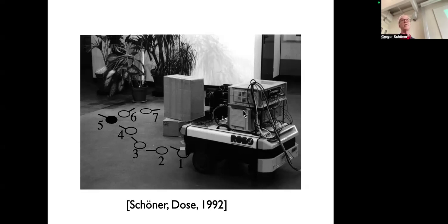And it had its perception of the world, this was one of the bottlenecks. So perception of the world was based on a special method where you have a stereo camera system. You can actually also use one camera at different moments in time, but we had a stereo system. And you're projecting the images from the two cameras onto the plane. You have to know how the camera is mounted relative to the plane. And so you're drawing on the surface the image that you would need to get that image into your camera. And that's a different image from the left and from the right. And the difference arises from anything that is not in the plane. So you can have a detection of anything that emerges from the plane. It's a kind of cool approach.